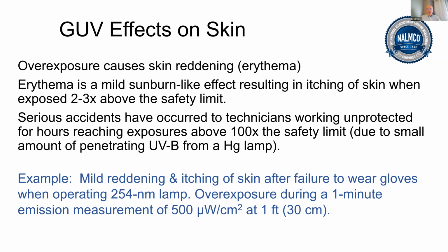So when you're making measurements for efficacy to see if it's really a good installation, it's really going to disinfect, you may have to raise your hand up into the treatment zone. So you need to wear protective sleeves and protective gloves for any skin that might be exposed up in the upper room.